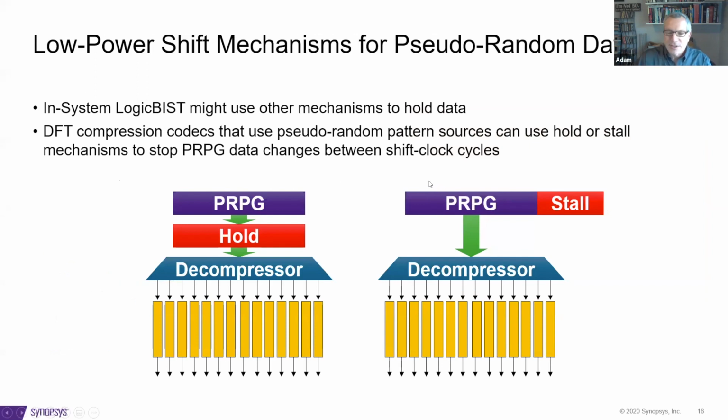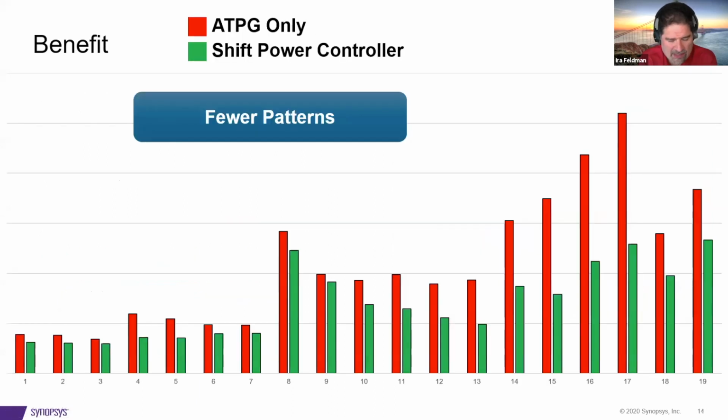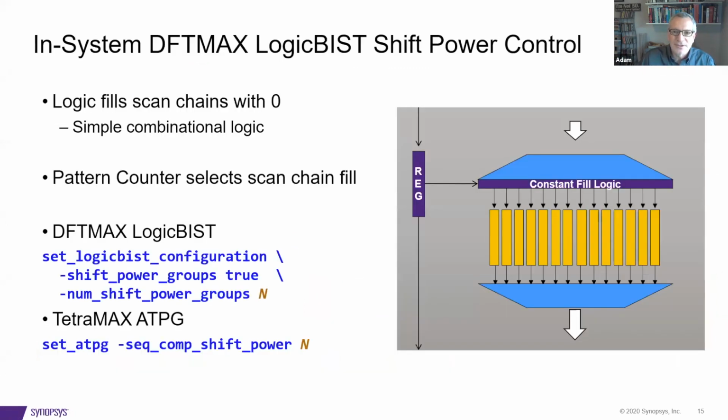Again, lowering. So two slides back when you talked about just lowering the number of vectors, I mean, that directly correlates into test time, correct? Exactly. This is rare. When you're trying to address power issues, it's rare that you get something back for your investment. A lot of times, at least from a pattern standpoint, you're going to expend patterns to lower your temperature profile. But in this case, we're adding hardware, and it works out actually very nicely.